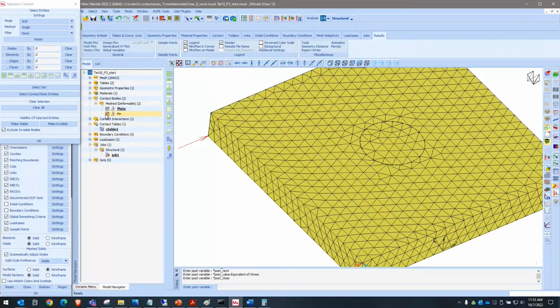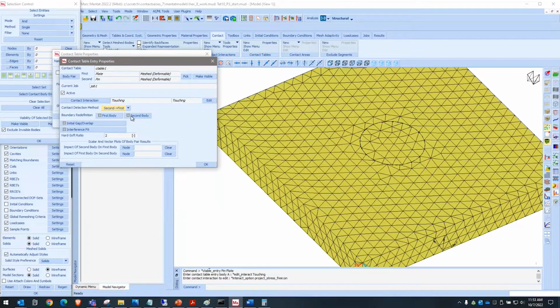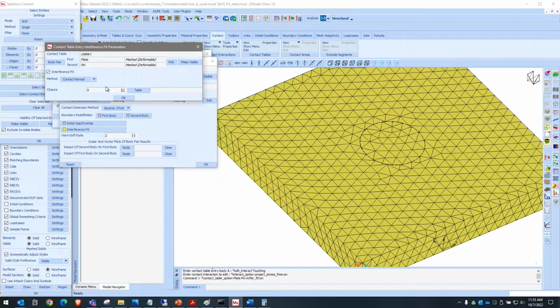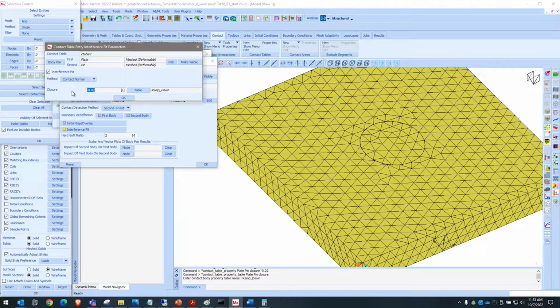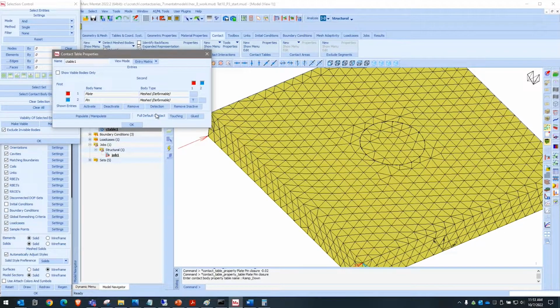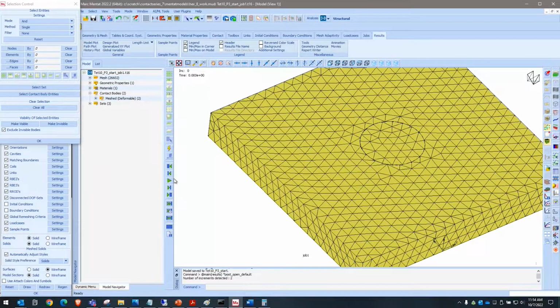But what we can do here is check whether that initial 20 micron was accurate enough. So again, we'll project stress free. I want this to be at minus 0.02. And then I'll use that same ramp down one. So initially I'll project to that amount of interference and then open up, or remove, the interference. Before I run the model, let's just take a snapshot of the results again.